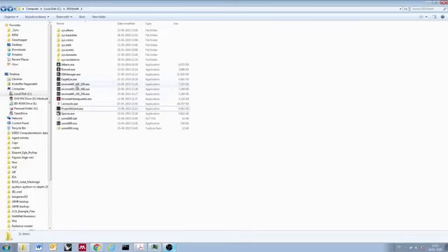ENVIMET itself is actually three different versions, and these three different versions are 40 by 100 by 100, 40 by 180 by 180, and 40 by 250 by 250. These numbers are referring to the amount of cells that the simulation tool is using when it's calculating the environmental impacts.